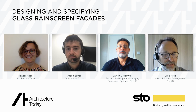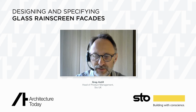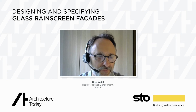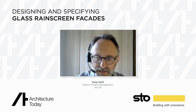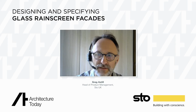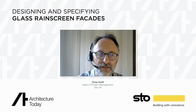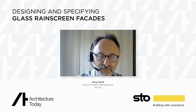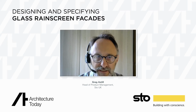Yeah, so the backer panel itself is made from perlite, which is manufactured pretty much by melting rock. It's a material that's been around for a long time. The perlite that's manufactured then has a small amount of epoxy binder added to it and is formed into the backer panel. This makes the backer panel particularly inert, so under the influence of cold or heat it doesn't expand or shrink, and it's also particularly resistant to moisture. So that gives us a good solid basis to bond the panel to.